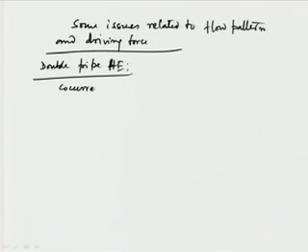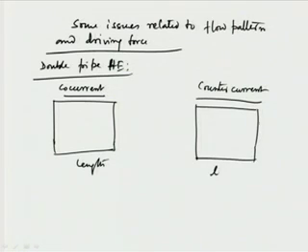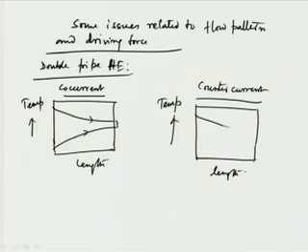So co-current and counter current. Already we have seen it, but if we say that this is the length and this is the temperature, the profiles, if we draw for co-current, appear like this and like this. So we can say this is the approach temperature, the maximum possible approach temperature. It can be at least 5 degrees centigrade or even more than that. This is the co-current case, and in a double pipe it's a perfectly co-current or perfectly counter current situation. So this is the hot fluid, this is the cold fluid.